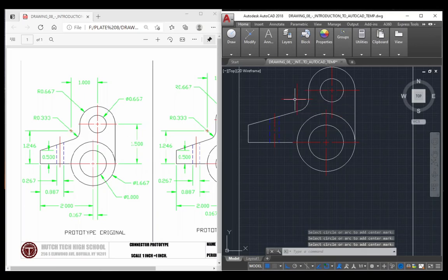So what I'm going to do is take this object, use the explode command, and break this down. They're going to go, Mr. Q, how'd you do that? I had that selected and I typed explode. If you type in explode, you can then go through and just select your item afterwards. I'm going to make sure I hit escape 2 times just so I don't have anything selected. Now I've got my entire object here.